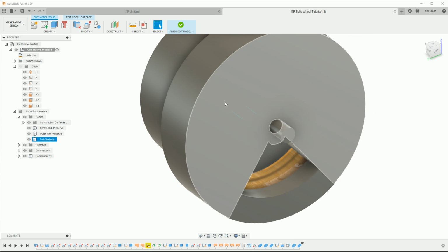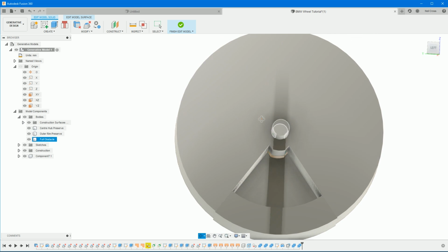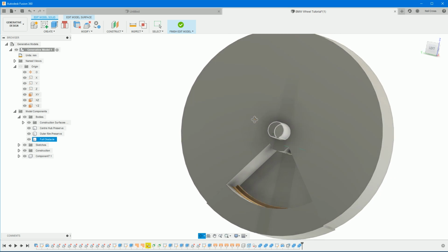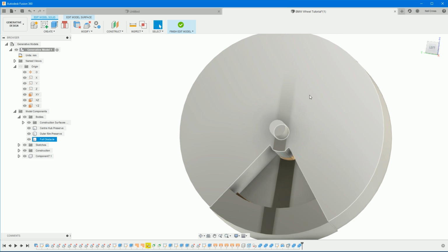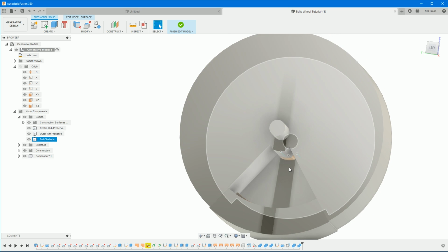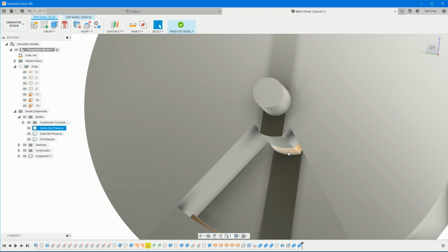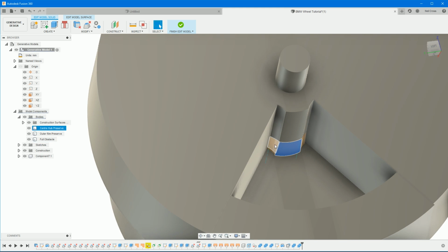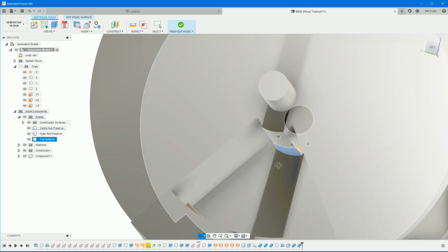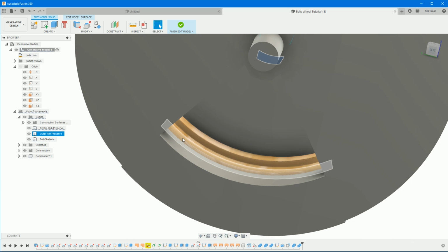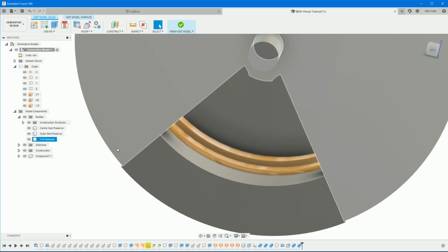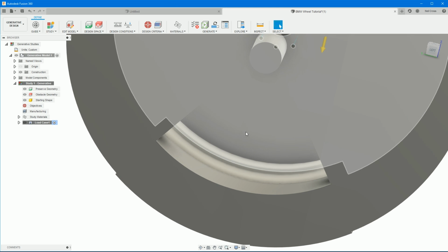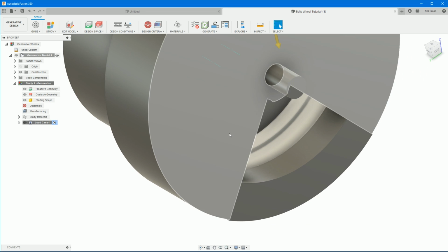So all of this huge, massive solid here, this is me telling the Generative Design module and the algorithm, do not grow material wherever this big massive lump of solid is. So I've exposed a region of the hub here, so it's free to grow material out of these faces and then into this section of the rim. Everywhere else is a no-go area. And that's what all of these features are at the bottom. You can drag the end of part along to see what I've done. Click Finish, Edit Model. And then we can start setting up the study.